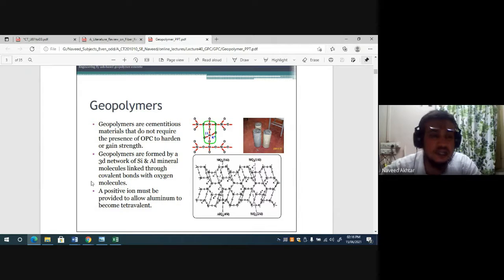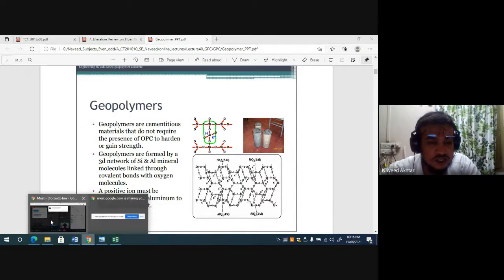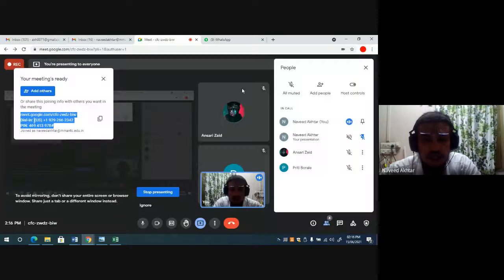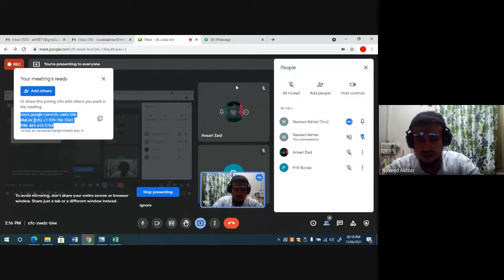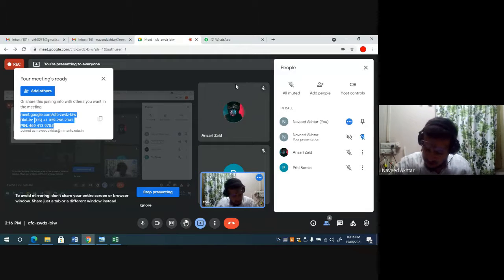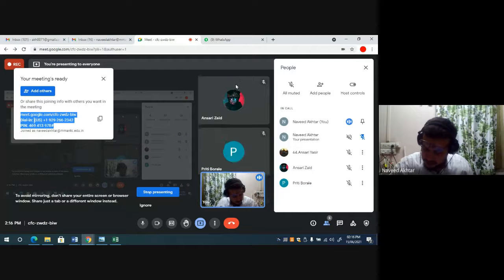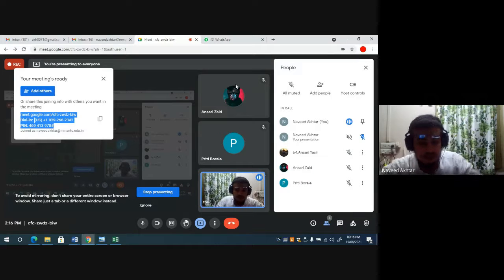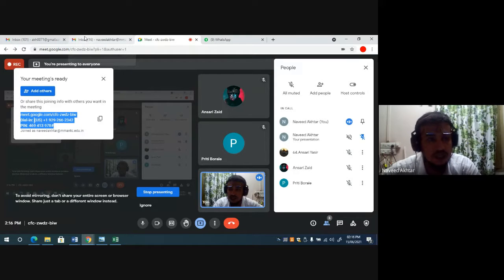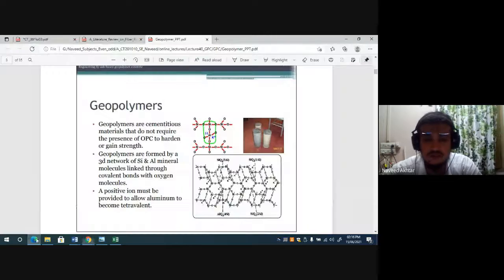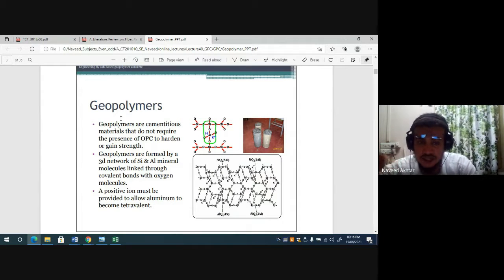In the case of ordinary concrete, the process is hydration. The calcium silicate hydrates are formed, and mostly they are responsible for the strength gain. That is the CSH gel, calcium silicate hydrate.